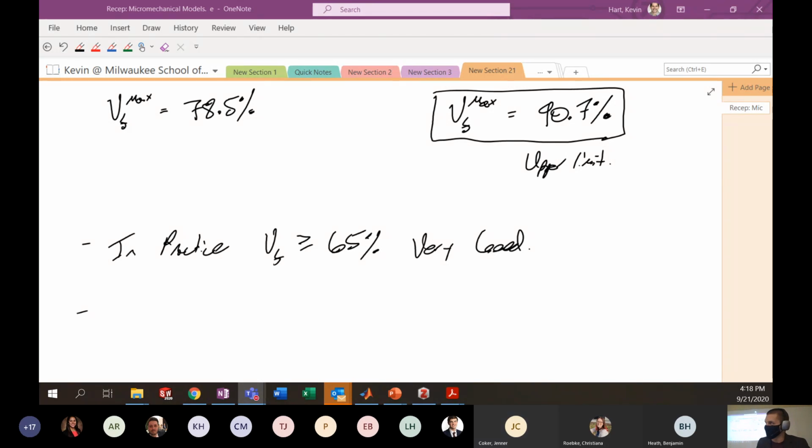Next question from the audience. What percentage is prepreg? When you get prepreg, it's usually a little high on the matrix, just because some of the epoxy will come out during the manufacturing process. But if unidirectional prepreg is handled and manufactured correctly, you're going to get it in the 65% range. That's how you get the 65%. It's generally gotten through prepreg autoclaving techniques. Okay?